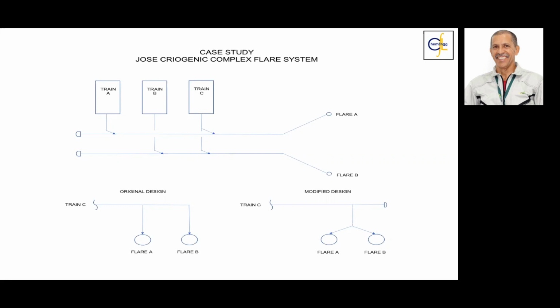What they did to try to control the system was close the valve manually on one of the condensers to get more water into the other. And I realized, so this is a bad design. If you are looking for a very good distribution, we have to do something.